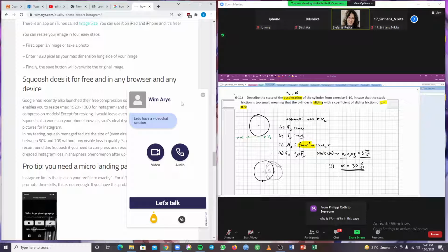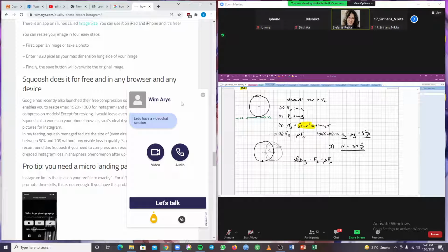We have this equation here, the equation of sliding friction as learned in Engineering Mechanics 1. In case of sliding, you have to use the sliding friction coefficient, and it's always an equal sign: Fr is equal to mu times Fn. And static friction, in our case rolling, would be Fr smaller or equal to mu0 Fn.